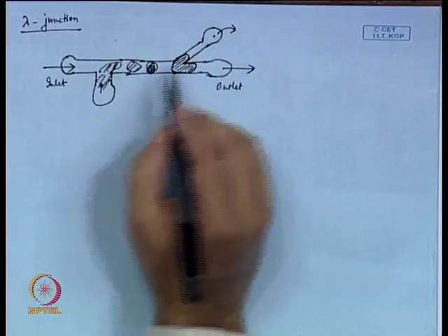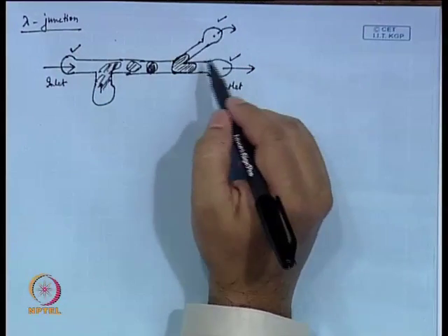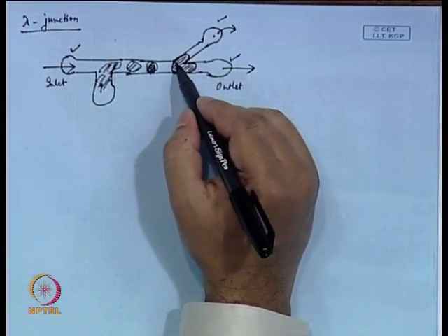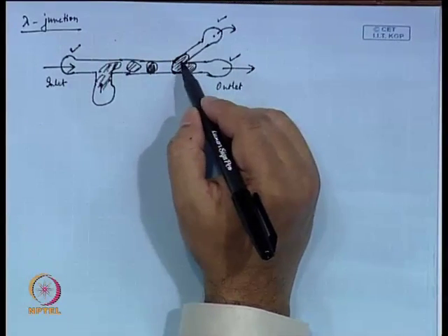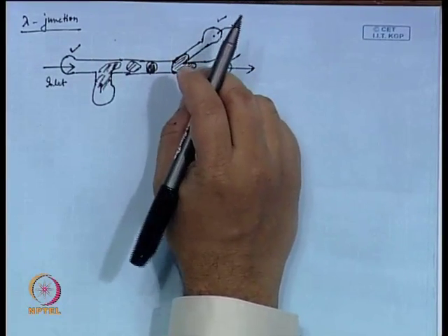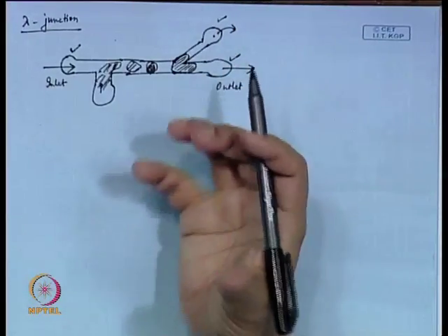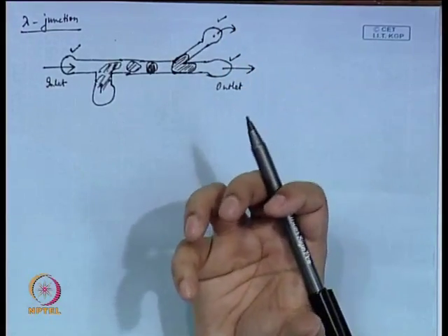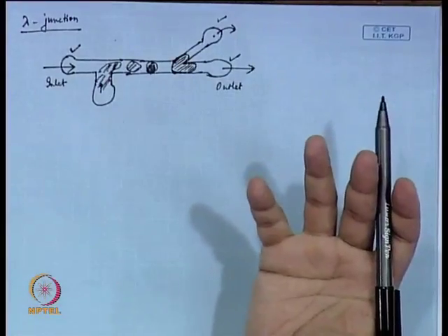Depending on what is the pressure here, what is the pressure here, and what is the pressure here, one possibility is that it can go in a little bit and later on it negotiates and it simply comes out. It goes in, and then you have interfacial tension which is pulling the droplet phase together. Why is it a sphere? Because there is some reason for it. So, why is it intact? Why is it a droplet? Why is it not a completely dispersed one?